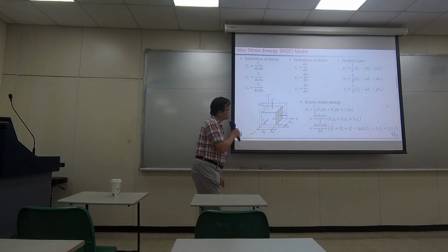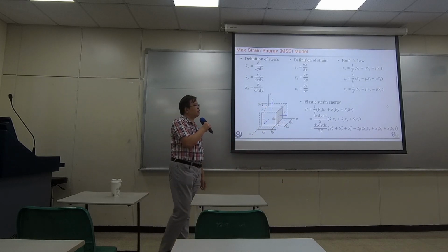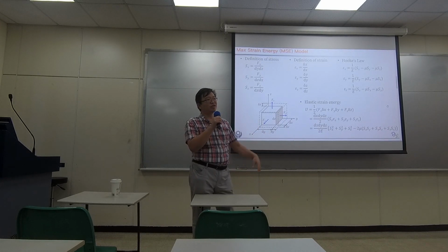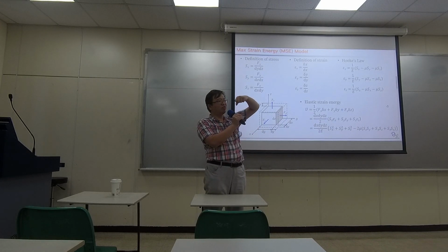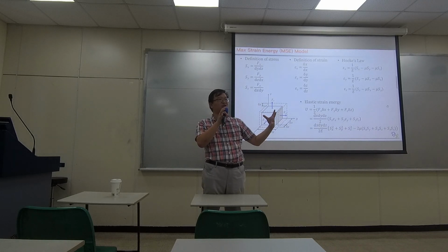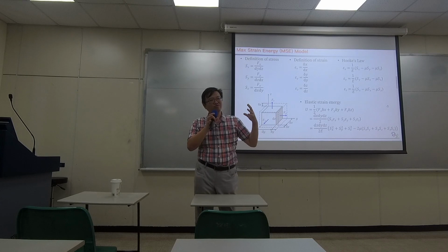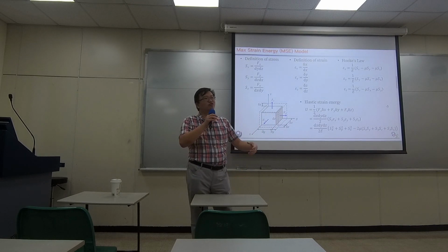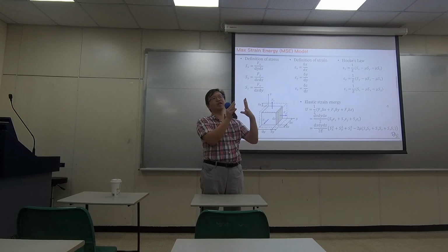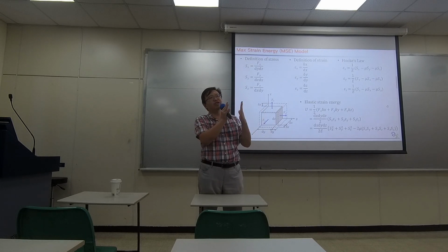It's a ratio. Okay? So there's something called negative Poisson ratio material. If you have a material that, when you pull up and down, actually expands horizontally, then the Poisson ratio is negative. Because usually if you pull something up and down, it shrinks horizontally, left and right.